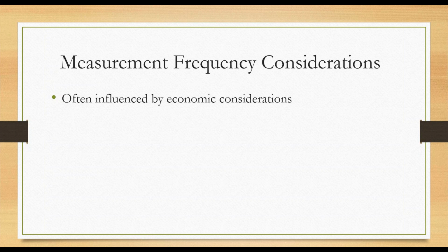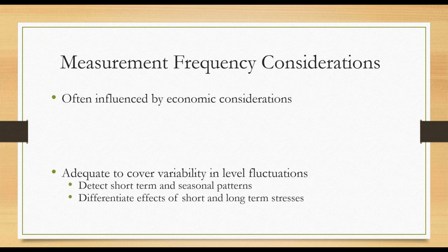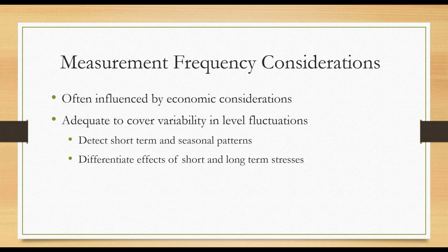So depending on the objectives and the economic considerations of your study, you may decide that you can get the information you would like and need for analysis without having to install expensive instrumentation, but go out and manually measure. You want to make sure that you have adequate coverage for variability and level fluctuations.